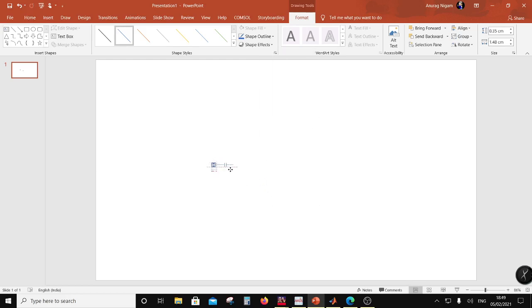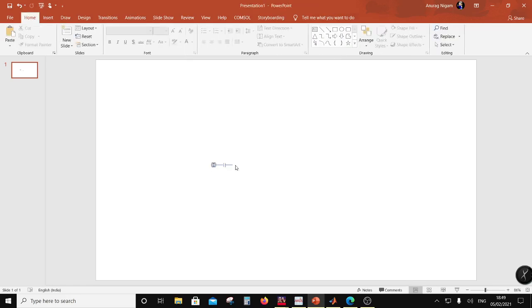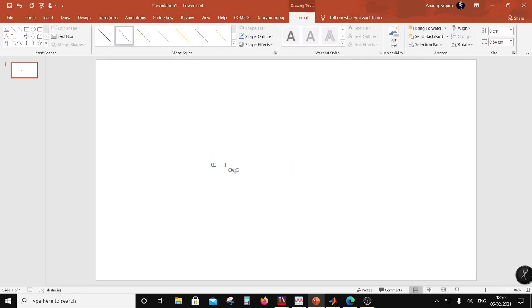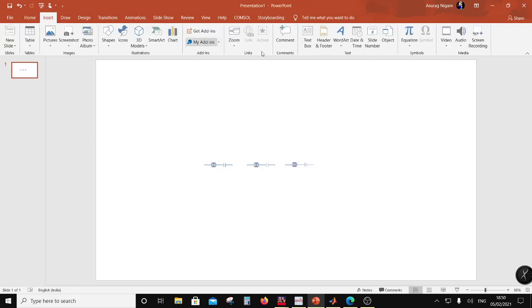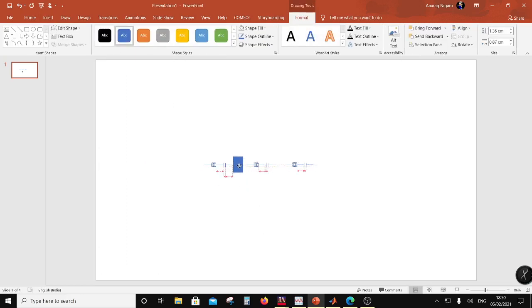So let's have a resonator like this. This is a series resonance, correct? And then there's going to be a shunt resonance. So the basic structure is that. Now if we were to implement this filter using these series resonances, in between I am going to put what is called an impedance inverter, Z inverse. A quarter wave line is an example of an impedance inverter, as we have seen in the previous sections.